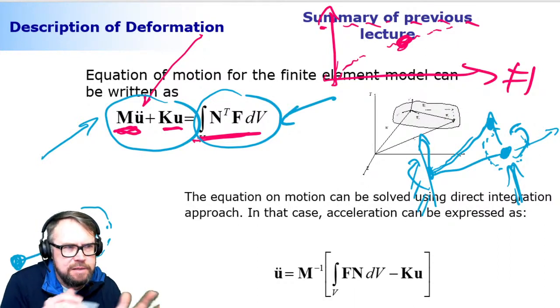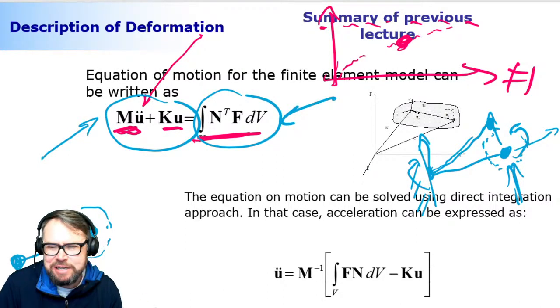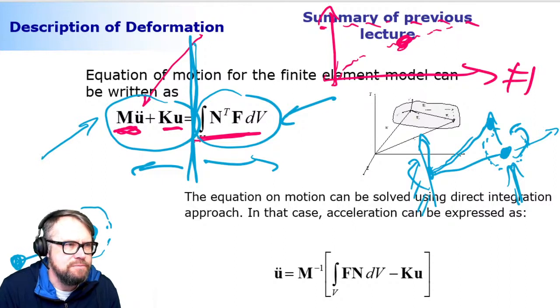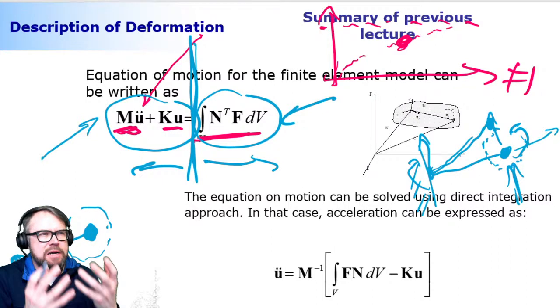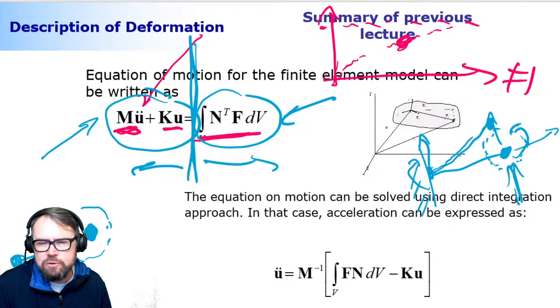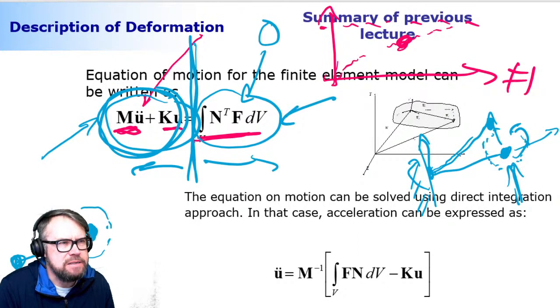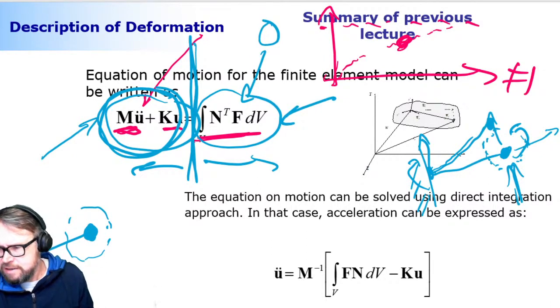All right, here was my explanation. In this equation we have the loading in the right-hand side and the features of the structure in the left-hand side. Now these deformation modes we can figure out by focusing on the left-hand side of the equation. Actually, we can conduct an eigenvalue analysis. That's the way of forcing the applied force to be equal to 0. We're just neglecting the forces because forces do not affect natural frequencies or the corresponding deformation modes. This is in the case of linear dynamics. We focus here on small deformation in linear dynamics.